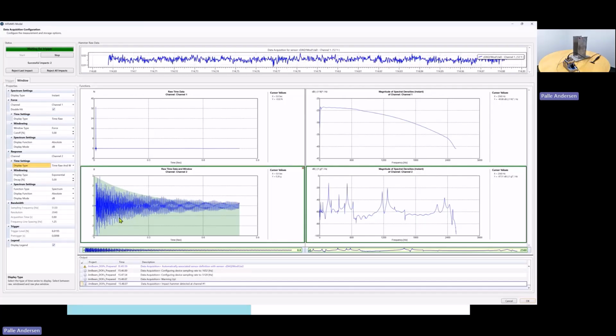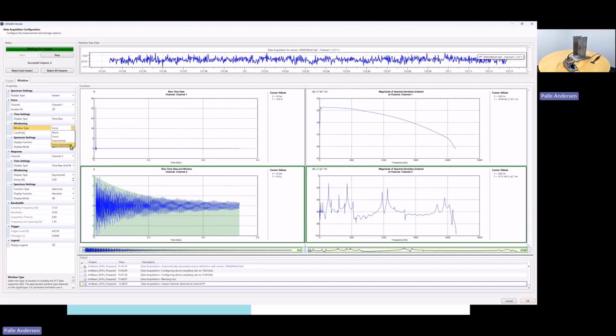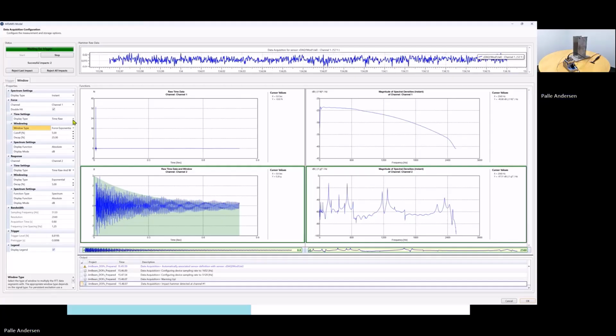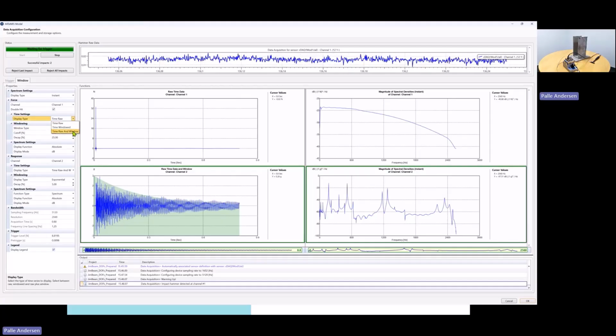When we divide, basically the influence on the FRFs will disappear, at least the height of the different peaks in the FRF will then be okay. So we also have to introduce a force and exponential window up here like this. Again, we can look at how it looks here.